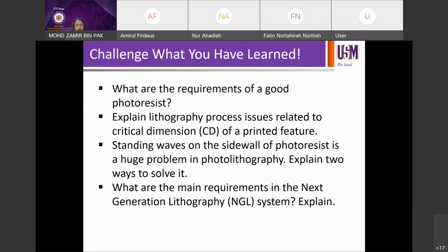Right, done. Low defect density, yes, of course. You don't want to have particles in your resist. They can affect the DOF, for example. If you learn about DOF, focus, and how the non-uniform resist coverage could affect the DOF, that will eventually affect the resolution of the printed patterns in this case.